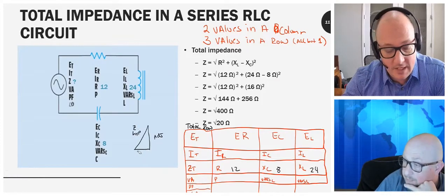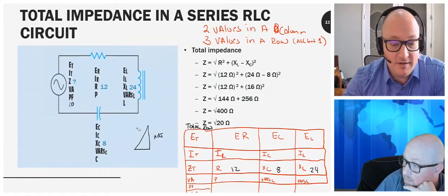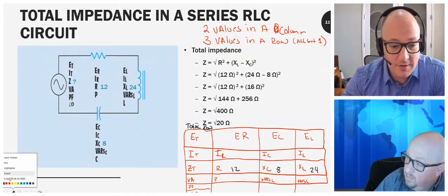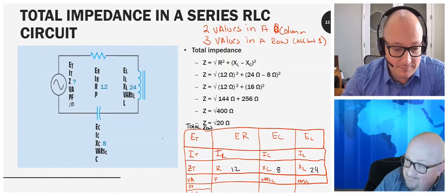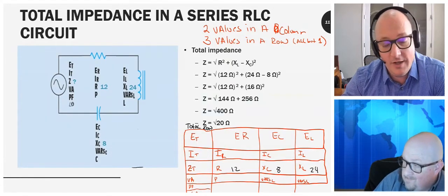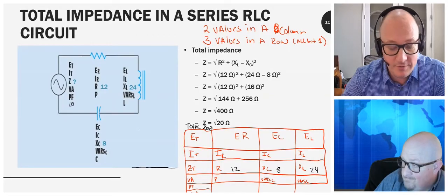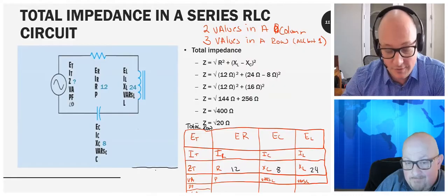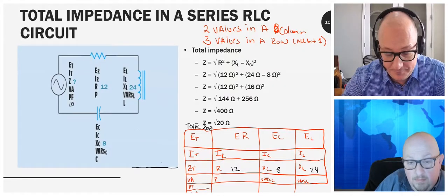How about that? An easy way to think of it is with the right triangle, because if you do much with vectors, you start with a horizontal line, and that's 0 degrees. We know that voltage and current are always in phase through resistance, so that's my 0 degrees.